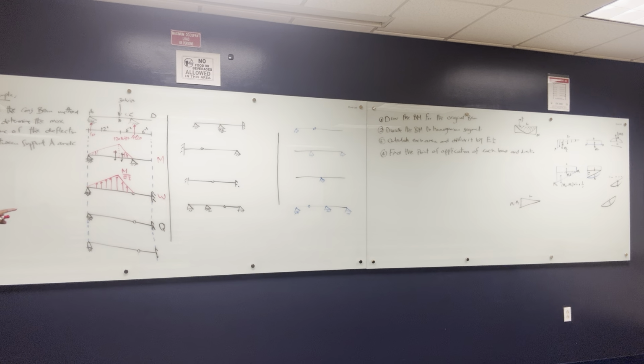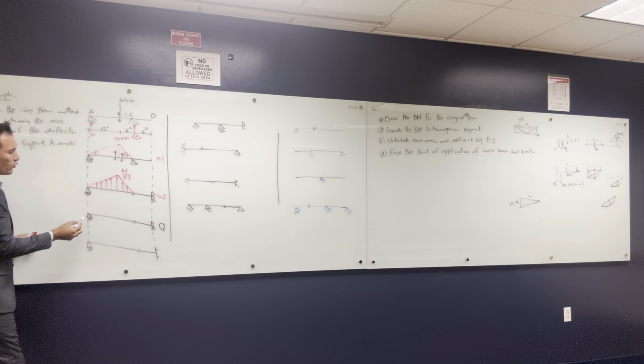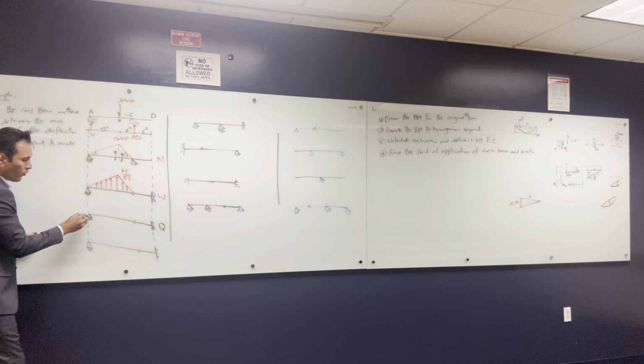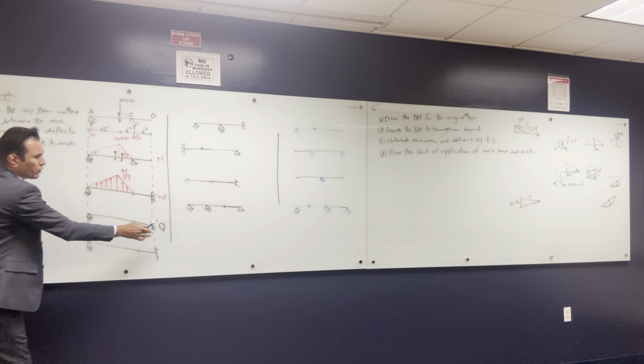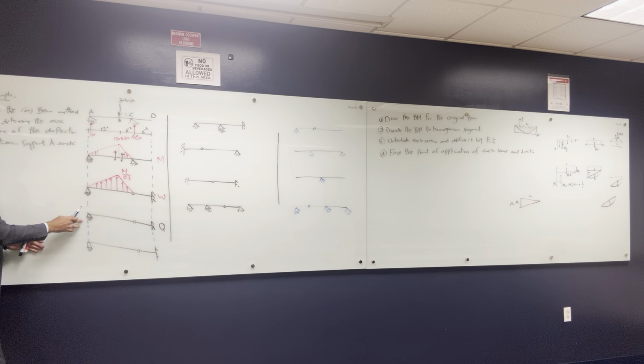Okay, so if I want to draw the bending moment and shear force diagram for this, by the way, the load is linear. What do you expect for the shear to be? It's gonna be first degree, second degree. Second degree. Why? Because this is first degree, so definitely the shear is a degree above this, so it's gonna be second, and this is gonna be third degree. So from my expectation, if I draw the shear diagram here, what is the value of the shear?